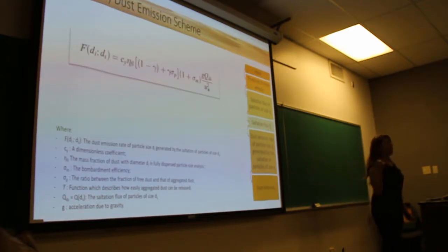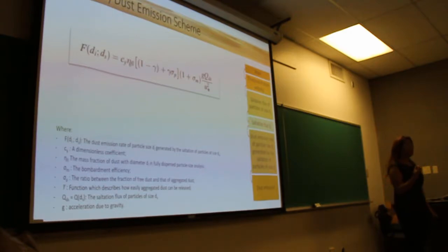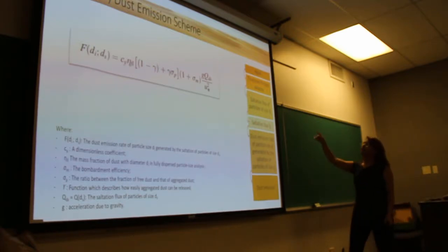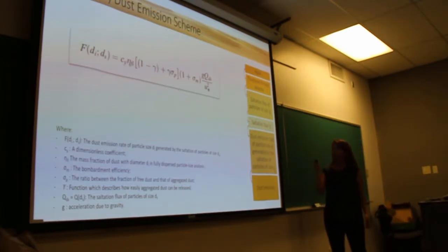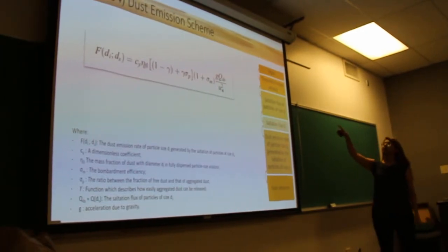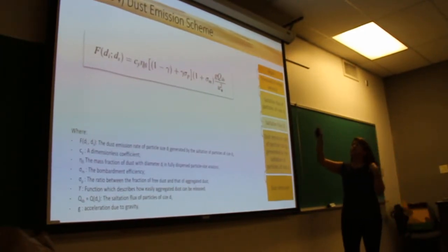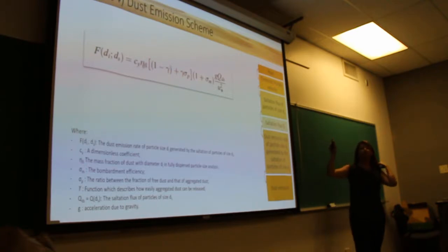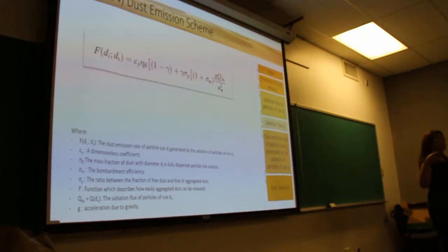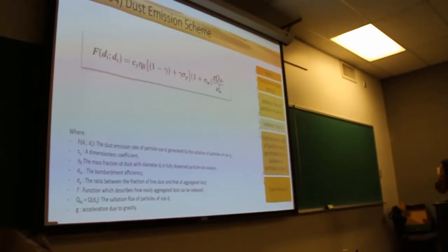Dust models are the key components of wind erosion modeling systems. Here you can see a general structure of dust emission models. We have some inputs, and we calculate the key variable, which is threshold friction velocity, which depends on soil texture, vegetation cover, and some other factors.